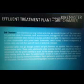The grit chambers for ETP are aerated grit chambers and vortex type grit chambers. In an aerated grit chamber, diffused air keeps organic solids in suspension as grit settles. In a vortex chamber, a vortex is created, the grit moves to the outside of the unit and gets collected.